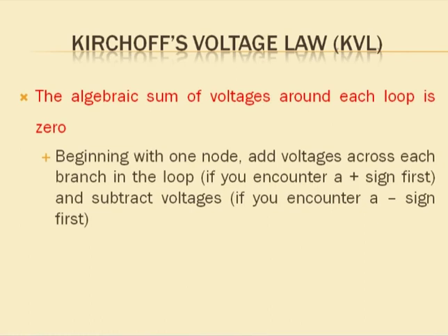That means if I move from one node to another and the voltage drops, the sign is positive. But if I travel from one node to another and the voltage is raised, the sign considered is negative.